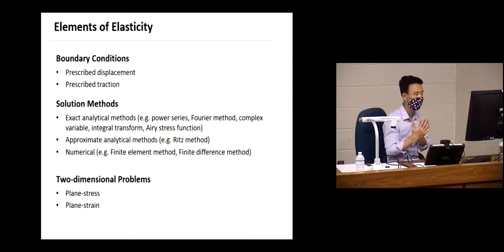Okay. So when we're dealing with, for example, very flat plates, a piece of, say, this small desk on the chair, this is a plane stress problem, right? We can approximate this as a plane stress problem because under the conditions that we load this small piece of desk, it's going to create stress that only varies in the plane of the solid.